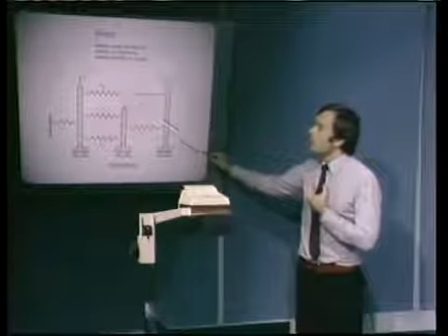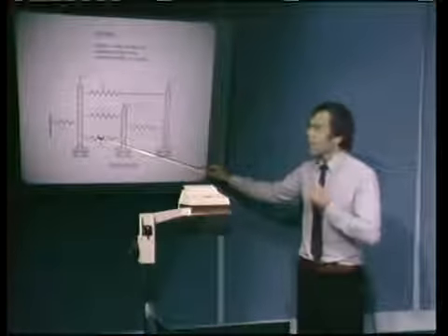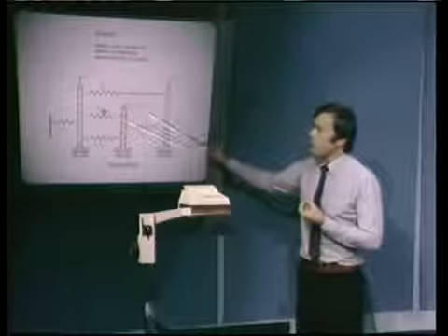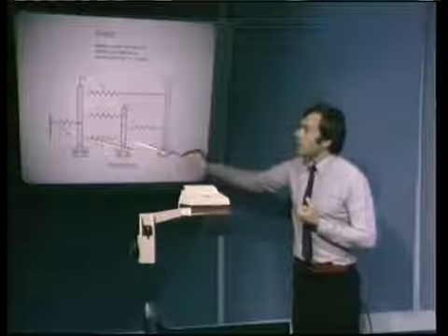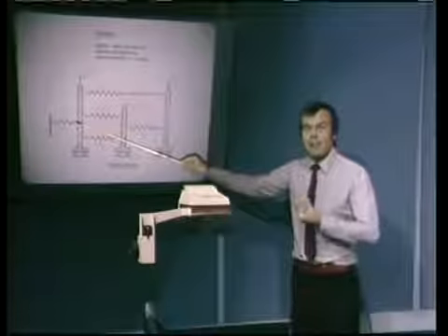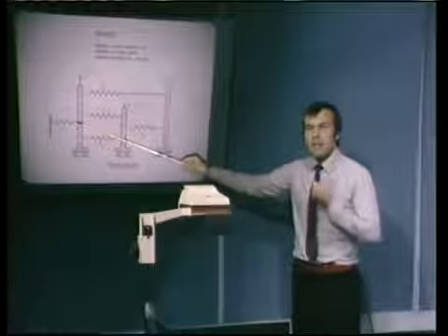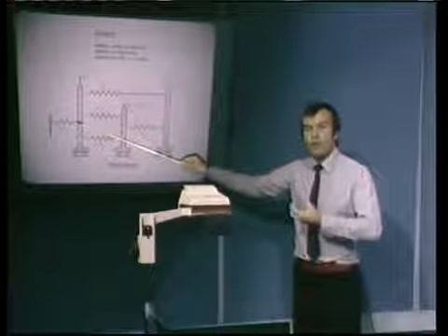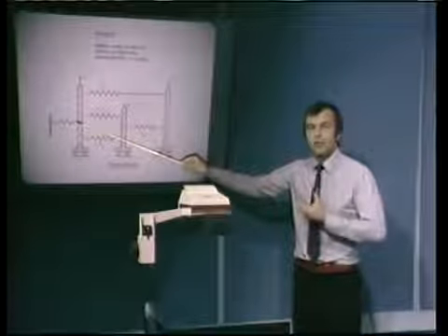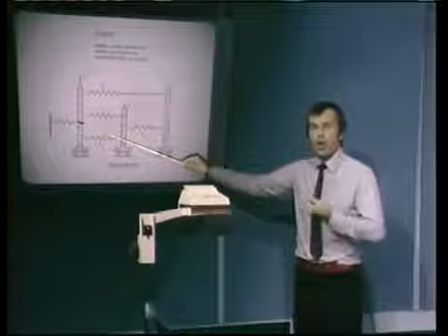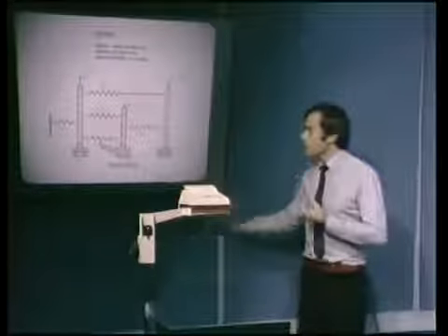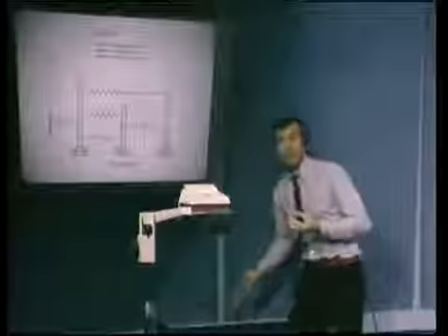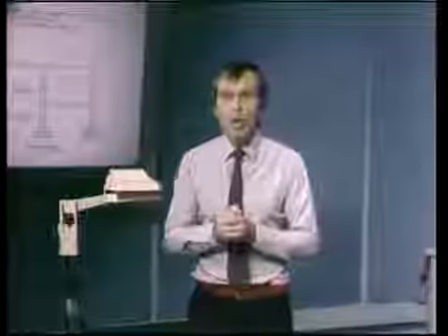But in this simple analysis, we are given directly the spring stiffnesses. And one other important point is that the spring stiffnesses here are exact stiffnesses. In a finite element analysis of a continuous system, we have a choice on what kind of interpolations we can use for an element. We have a choice on what assumptions we want to lay down for an element. And then, using different assumptions, we are coming up with different stiffnesses of the element domain that we will be talking about.